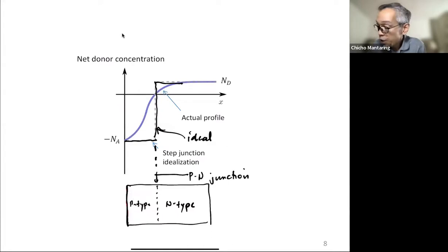The point at which the semiconductor material transitions from p-type to n-type is our PN junction. Note that you cannot create a PN junction by just gluing together a p-type and an n-type. It has to be a single crystal. The entire solid has to be a single crystal with one side predominantly p, and the other side n.